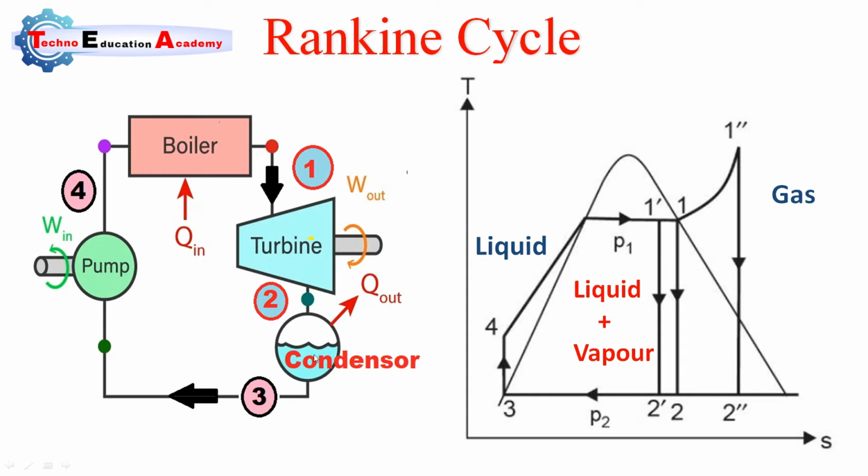Then the condensate is conveyed through the pump, and ideally in a pump the process is isentropic compression, but practically it is adiabatic.